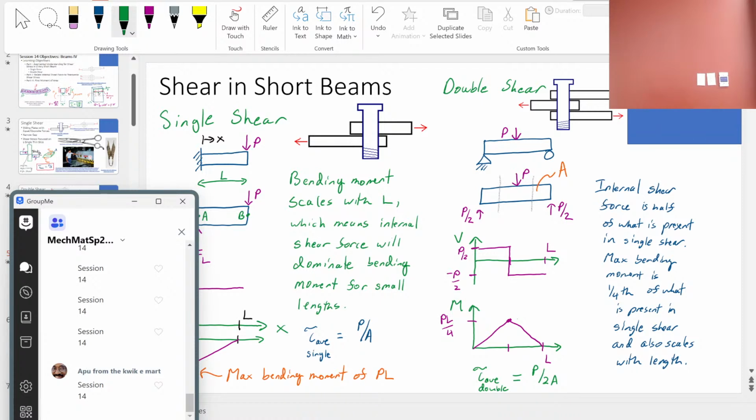That is the full. We agree on that, right? One of the reasons why we do these exercises is because we often get confused. That's what I'm trying to say: bending stress is at like half of shear, so that's got to be half the height. You guys are looking incredulous at me. That would be considered the variable y, right? But for this equation, right? Well, now you're doing transverse shear stress. That's different. So there's no y there.